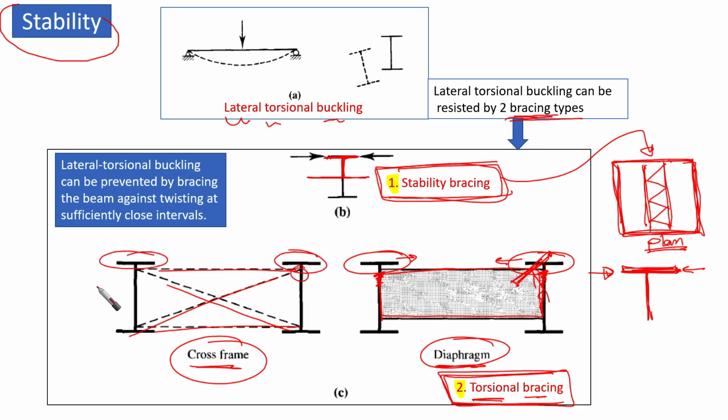and the flange. Okay, remember that this part of the web is considered very important in stabilizing the flange itself. If we could stabilize this part, like the neck, if this is the flange, for example, here, and this part which is directly underneath the flange, this neck, if we could control it, then the flange would not go laterally, or will not twist after that.